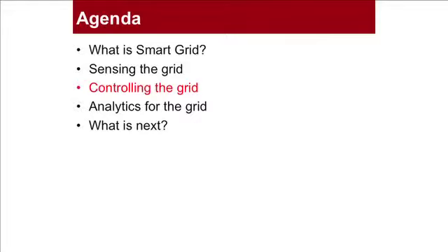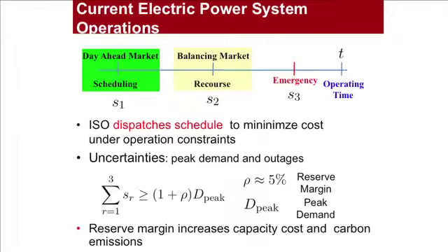Right now, the way it's done is that you assume the wind and the solar energy that's going to get produced is whatever you forecast plus 3 times the standard deviation of your forecast, or minus 3 times the standard deviation of your forecast, to be conservative. You take that assumption and you do everything as if nothing is unpredictable about wind and solar.